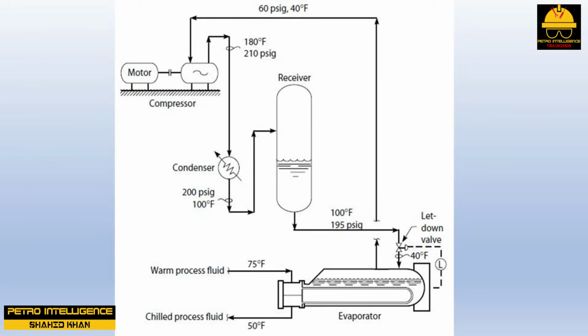The basic process flow of the refrigerant system is: 1. The compressed refrigerant vapor is discharged from the compressor. This vapor is superheated, meaning that it is above its dew point temperature. 2. The vapor is next cooled and condensed in the refrigerant condenser.